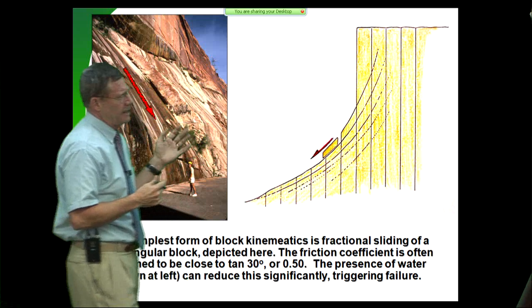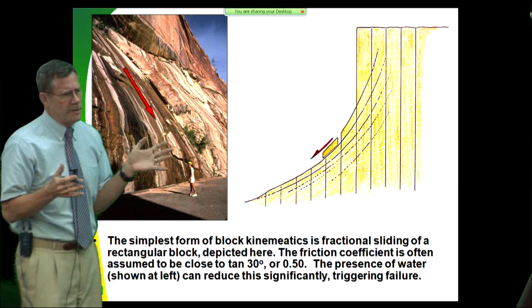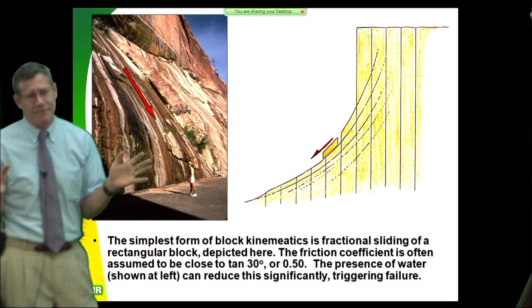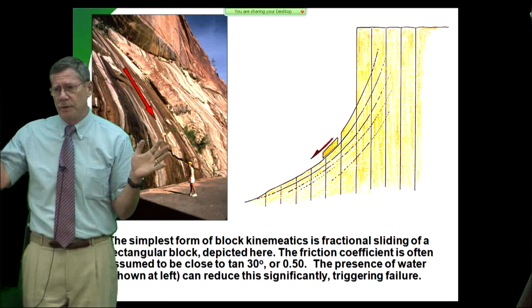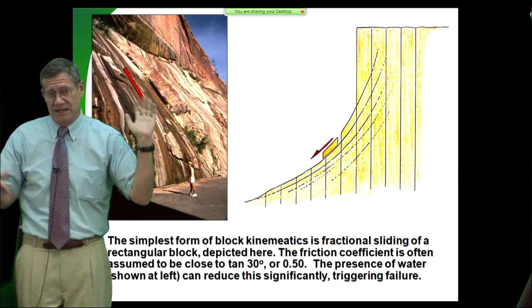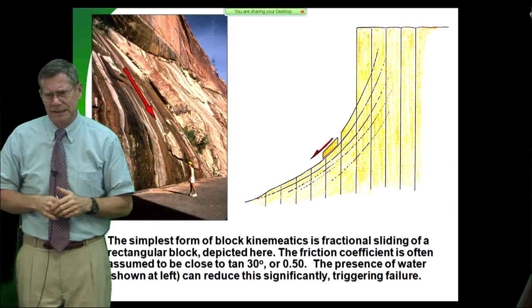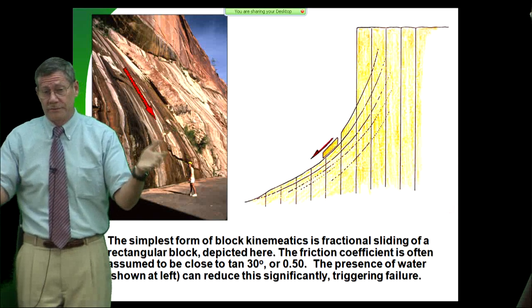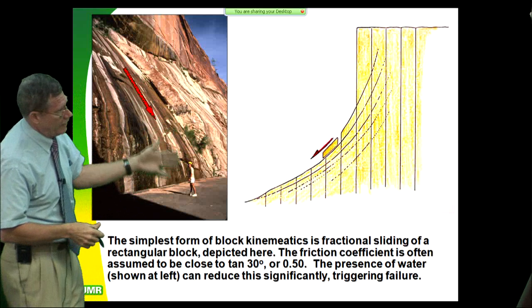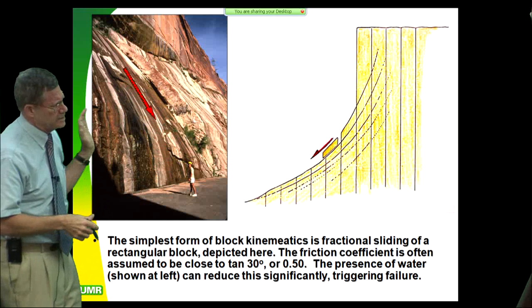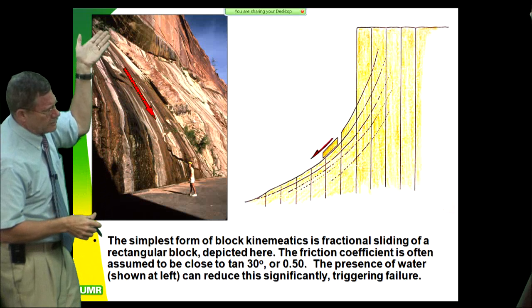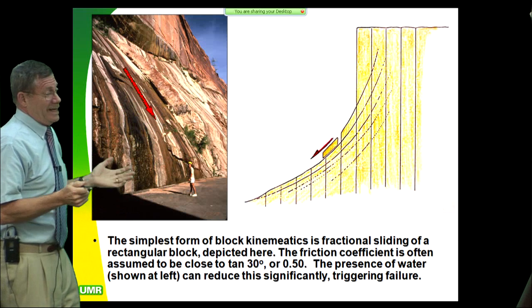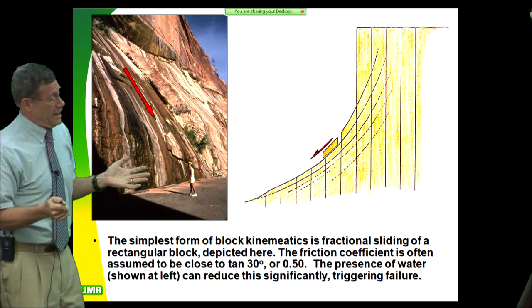And what happened at Glen Canyon, they had so many joints there, so many valley side joints, they were running 10,000 gallons a minute seepage through both abutments. 10,000 on one side, 12,000 on the other side. And this thing was just smoking with water going through. And so you can see the water coming out over here on the downstream side, hundreds of feet downstream. Here's the water coming out down the sheet joints. So that can easily trigger a failure. That's not going to be real hard.